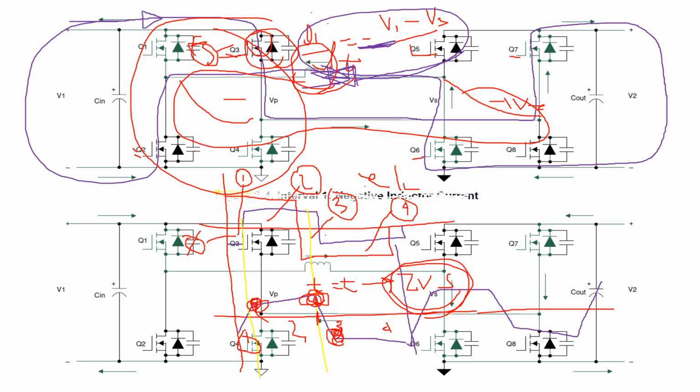While it does this, it makes the voltage across the switch either 0 or V1 on the primary side and V2 on the secondary side. In doing so, one capacitor will be fully charged and the other discharged. When the discharged capacitor reaches 0, it forward biases the diode, and the diode conducts.